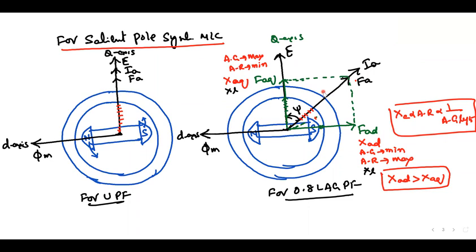Each angle has a different reluctance. Can you take that many reactances? No. So we can say it is an approximation. Instead of taking thousands of reactances, we take two reactances. At any power factor you draw the FD and FQ components, forget about their magnitudes, but FD will always find the same reluctance, the minimum.